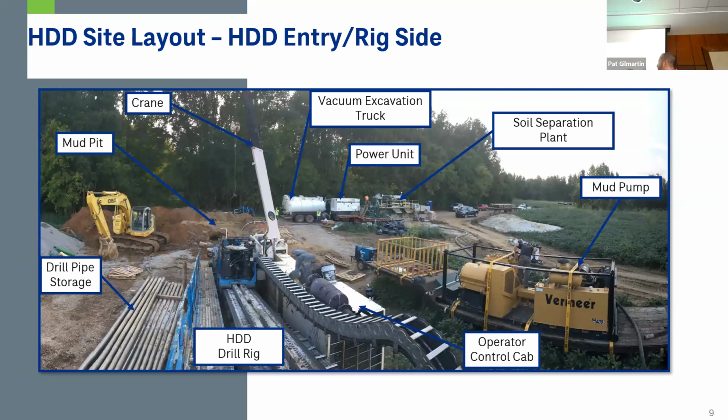You've got your soil separation plant over here, where basically once they're pumping out of the pit, they use a screening device in order to get the sands and clays and various soil or rock materials out, and then are able to recirculate so that you're not constantly bringing new water and mud into your site.